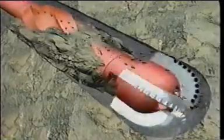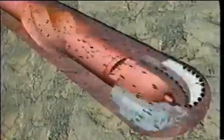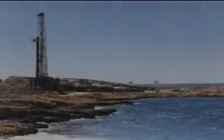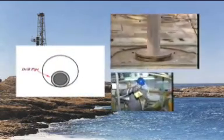In order to effectively remove the cuttings from the high-angle portion of the well, we must mechanically disturb the cuttings either with turbulent flow, which is impractical in hole sizes over 8.5 inches, or through pipe movement. Here, the addition of pipe rotation at 150 RPM effectively stirs the cuttings into the flow regime. Notice the hopping motion of the cuttings as gravity pulls them back out of the flow and the pipe movement pushes them back up. It's not just rotation that pushes the cuttings into the flow regime, but a combination of high rotary speed, pipe eccentricity, and mud rheology.